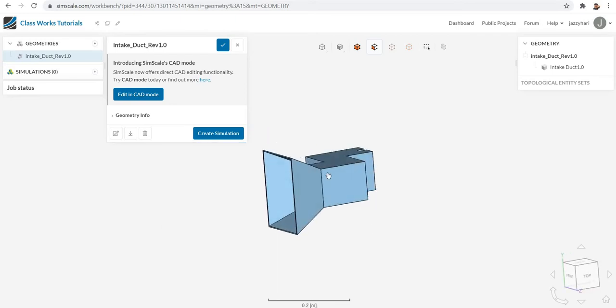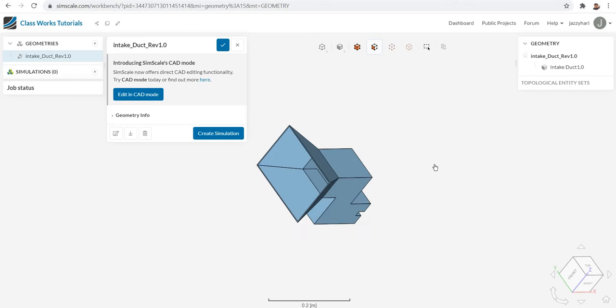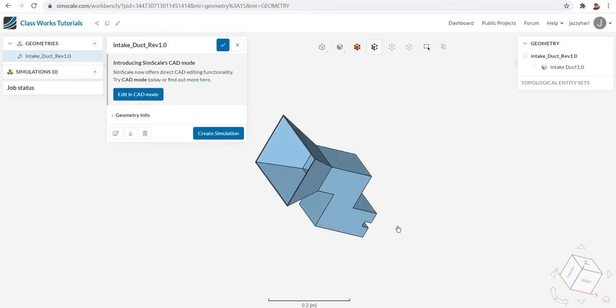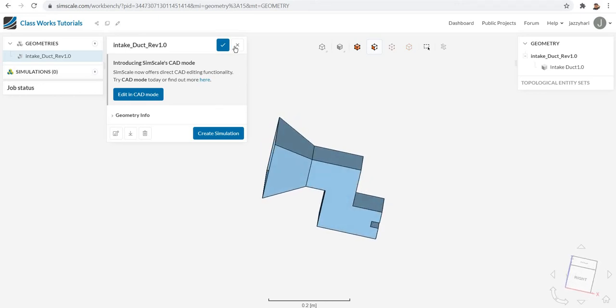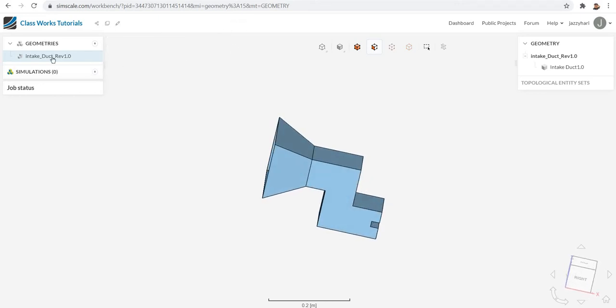For doing the computational fluid dynamics, we need the flow volume inside this duct. So this manifold inside volume we require. For that you can just click here, then go to add geometry operation, where you can go to open flow volume extraction. You can go to open inner region. So the inner region we are going to extract.